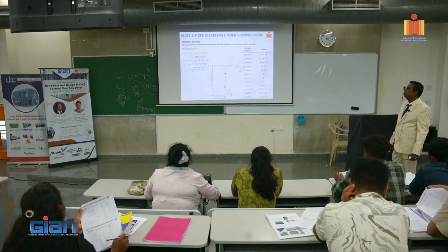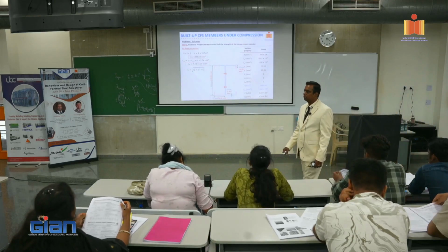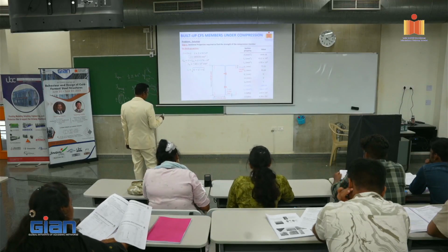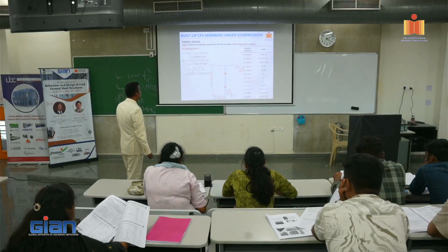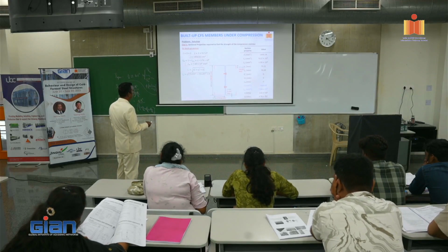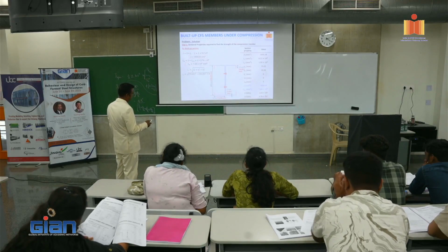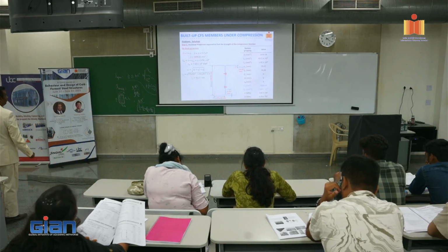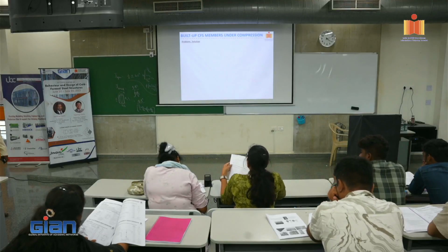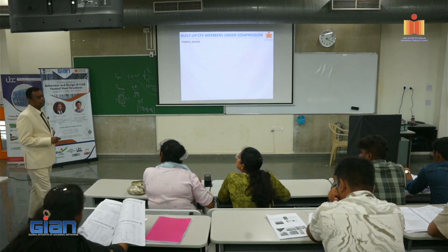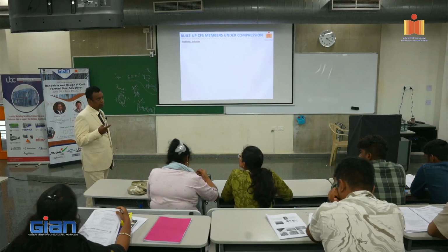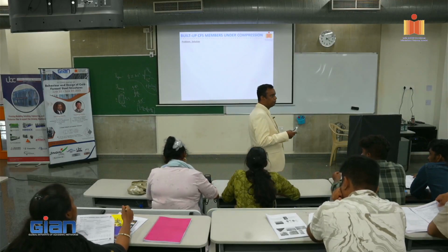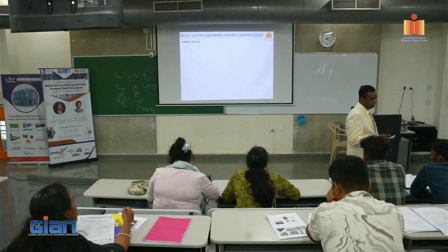Right, now you have to calculate R0. R0 is Rx square plus Ry square plus X0 square. So X0 is 0 here, so you have 75.22 plus 33.28, which we calculated, plus 0 gives you R0 equal to 82.25, right? Now you got R0 also. Why do we calculate R0? There is a reason for it. Because we have to calculate Pt, which is the load due to torsional buckling. That includes R0, right? So without R0, you cannot go further. So we are slowly building up, right?